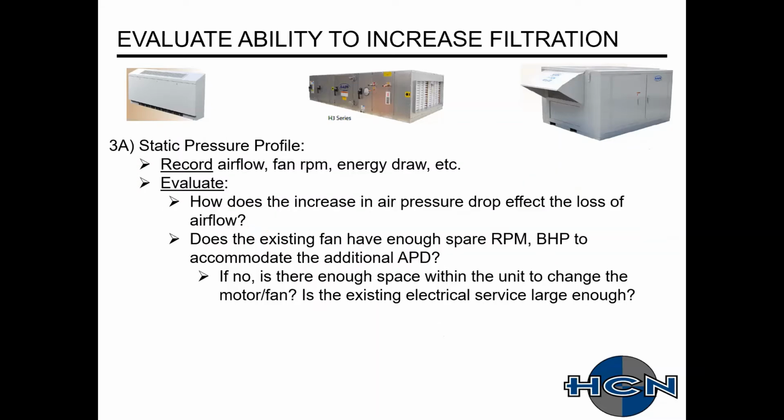Excuse me. So just diving into what a static pressure profile is. What they want you to do is record your airflow, your fan energy, your RPM, et cetera. Next step would be to evaluate how the increase in air pressure drop from the higher filtration affects the loss of airflow. And then, as I mentioned before, you want to look at whether your existing fan system has enough spare capacity to accommodate the additional pressure drop.